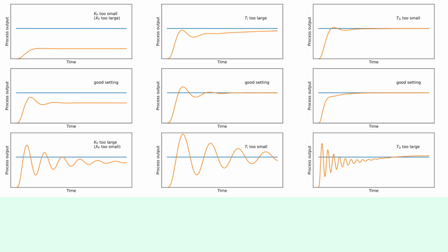Even the best controller won't work well without proper tuning. Tuning means adjusting how strongly the controller reacts to errors. If it reacts too aggressively, the system overshoots or starts hunting around the set point. If it's too slow, comfort suffers and energy use increases. The goal is balance, quick enough to respond, but steady enough to stay stable.